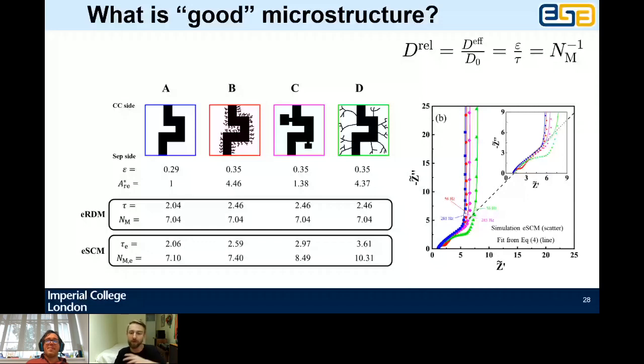Because of course, don't forget, there is no one particular good battery microstructure. It should be paired to what you actually plan to do with the cell, if you want an energy cell or a power cell, whatever. Okay, and is it constant? Brilliant question again. I don't know. The imaging is of course very difficult to do operando at different states, especially, for example, with a silicon anode, where these materials are hugely changing in size and morphology during different stages of lithiation. I'm sure these transport properties would be radically different at different stages. So I think it's a fantastic question. If anyone's got any data that could show it, I would love to see it.